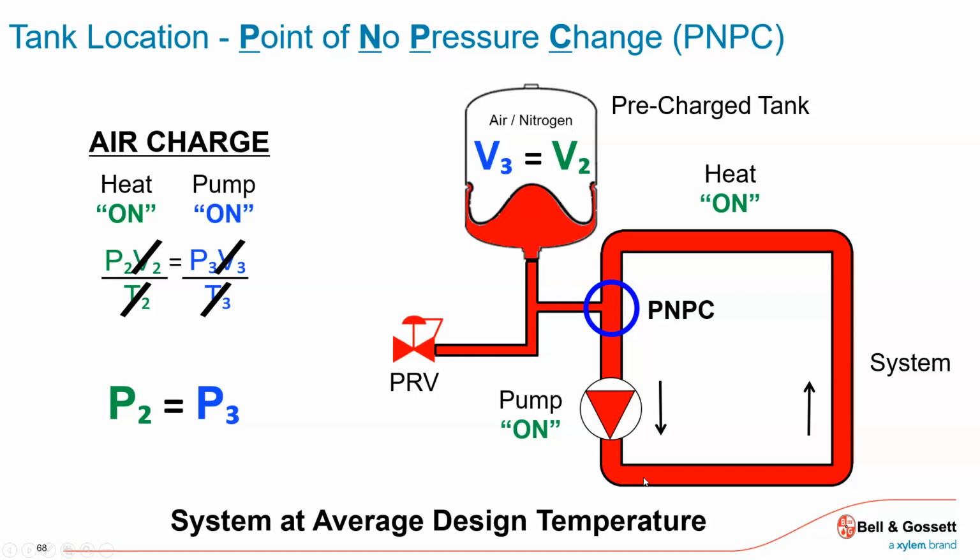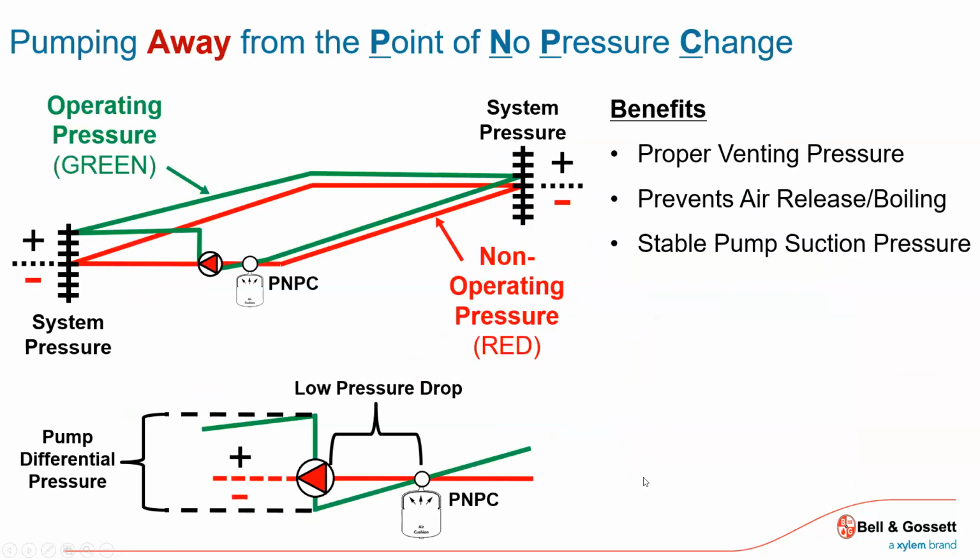And I bet you in most of your firms, when you go back, you'll look at these designs, these standards, and you're going to see that all of your pumps, whether they're inline or the big base mounted pumps, are almost always going to be located so they're pumping away from your air separating devices. And right beside that is going to be the connection, your line to some type of bladder or diaphragm tank.